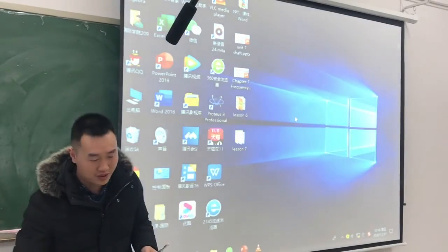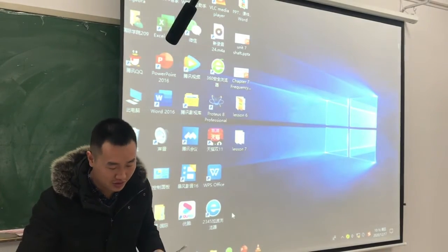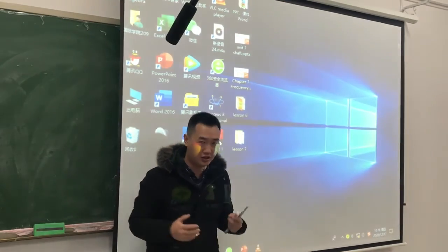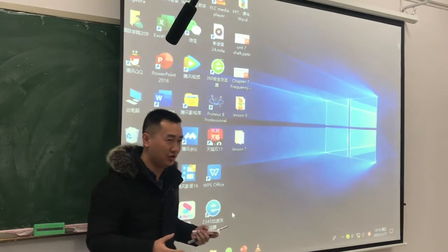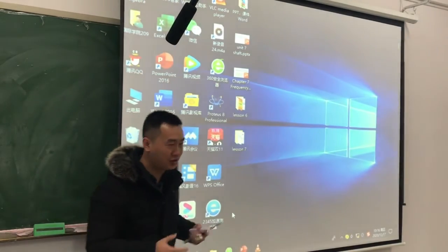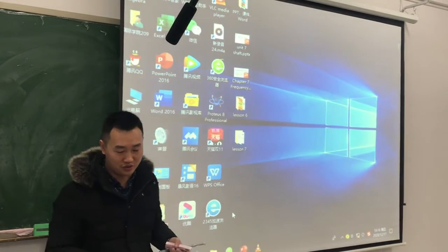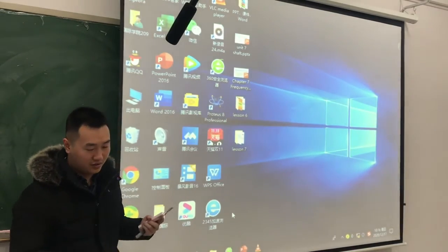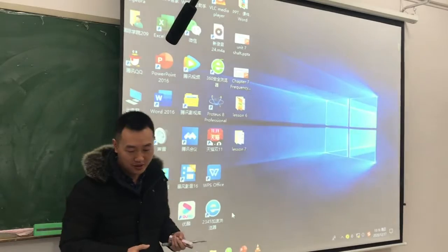In fact, you can think about how we measure geometrical tolerance. These days, we use a machine to measure it. For example, for circularity, we have a circularity meter to measure it. There are specialized machines to measure certain geometrical tolerances. Some are old-fashioned, manual measurements, and some can be measured by specialized machines. We will do 2 experiments later.